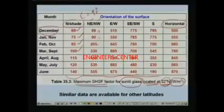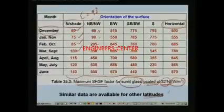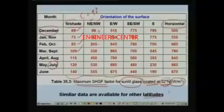ASHRAE handbook gives this similar data for other latitudes also, for example 24 degrees, 40 degrees, like that, right. So, from this table you can calculate what is the maximum solar heat gain factor. For example, I would like to find out during the month of July, what is the solar heat gain factor through a south facing window. Okay, that value is given by 230.